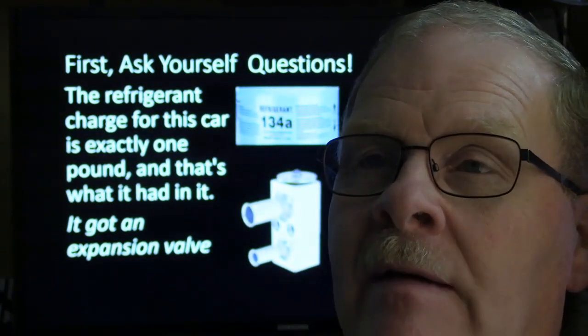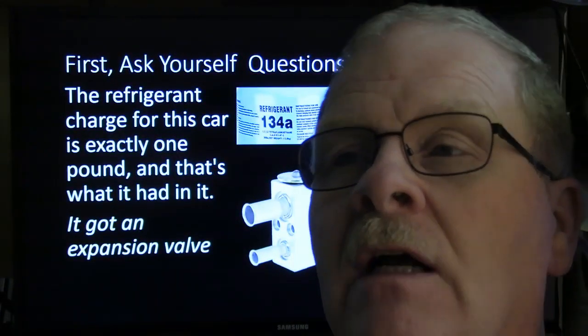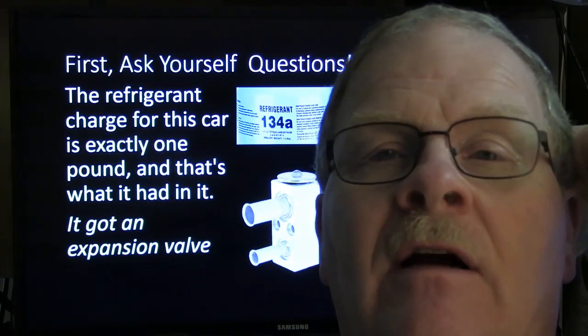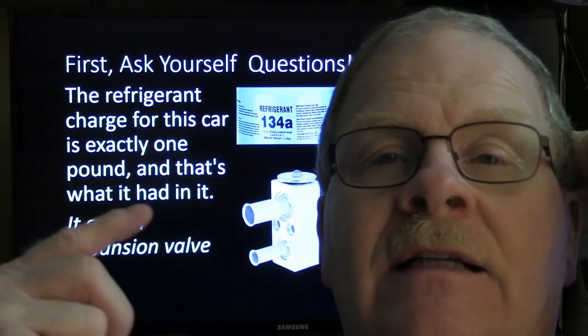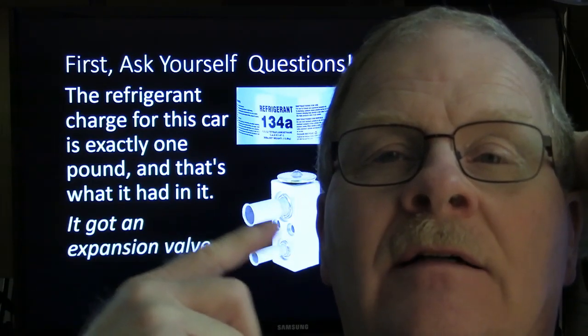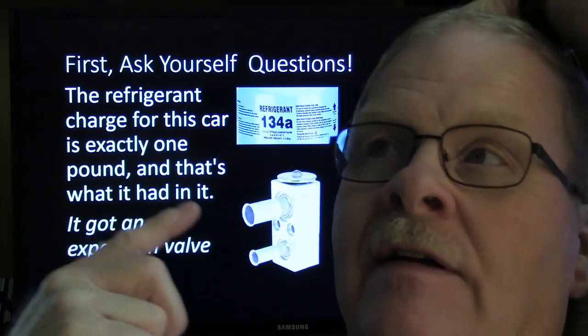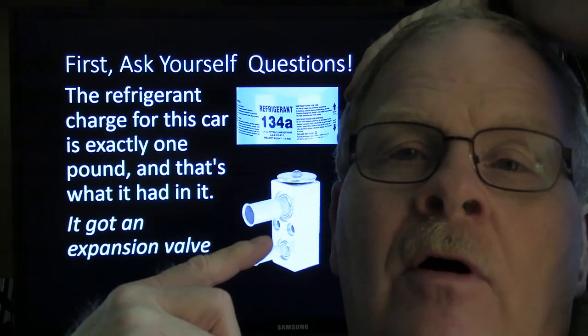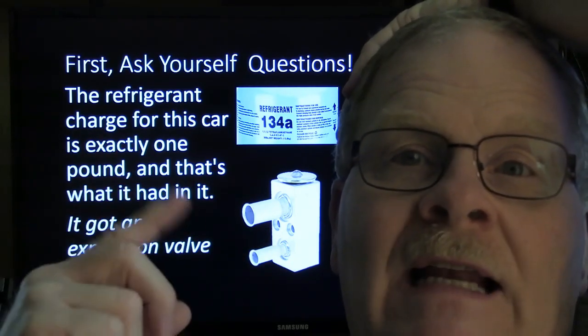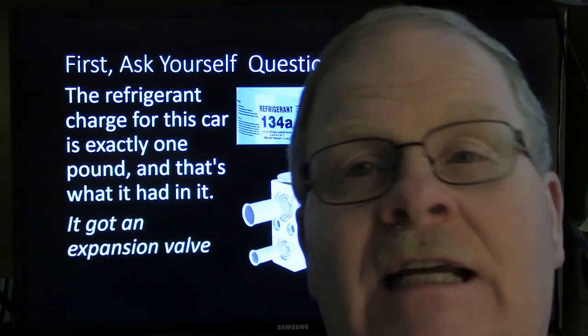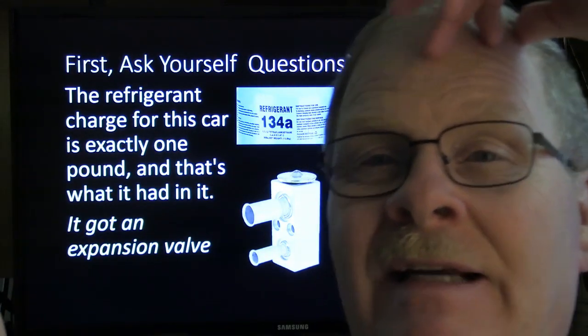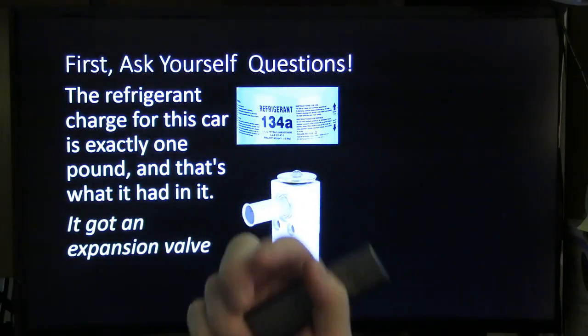So she didn't want to pay them $1,500 to do all that work, so she basically brought it over there, and I let it run until it quit cooling. And with my gauges on it, I could tell something had gone wrong in the expansion valve because the pressures went wacky like that, and we lost the coolant. Put a $16 expansion valve on it, and she had good cold air, and she still has to this very day. And that was like 3 or 4 years ago.